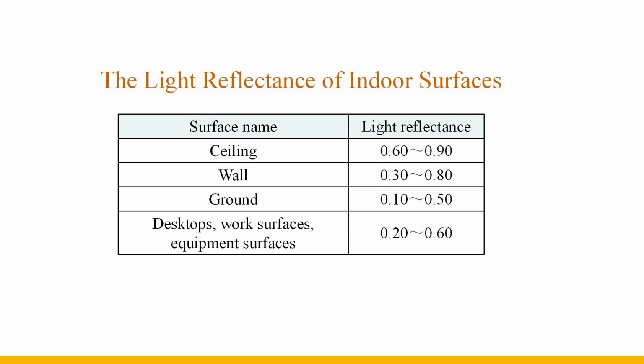When the natural light is insufficient, the color temperature of the artificial light source should be as close as possible to the color temperature of the natural light, so as to prevent the color viewing discomfort caused by the color difference of the light source. Since light enters the room through colored glass, the spectral distribution of the light will change, thus changing the color of the light, resulting in poor light color.